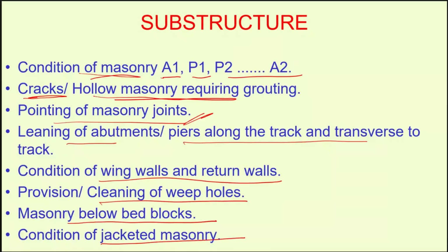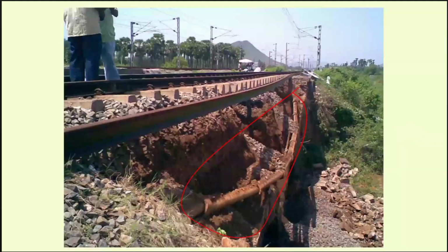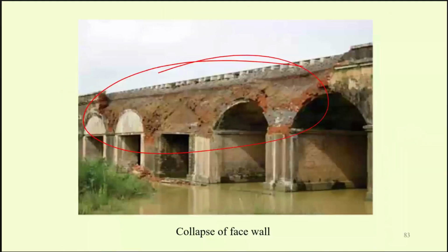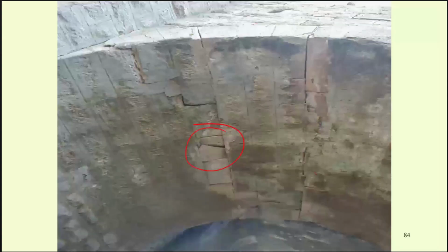See, this is the case where the structure has finally fallen like this. This is the broken stone. This is the crack development. Some pointing has been done. Like that, all those things you need to observe and see.